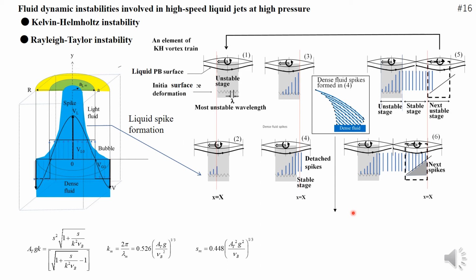The classical inviscid linear stability analysis predicts a growth rate which is not acceptable because an infinitely short wavelength dominates. The viscosity tends to suppress the short wavelength deformation. The frequently cited dispersion relation for miscible dense and light fluids is found in Chandrasekhar's book, for example. Unfortunately, this is not acceptable either because the maximum growth rate at k equals 0 is unphysical.